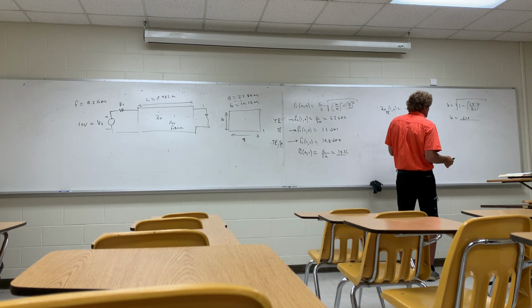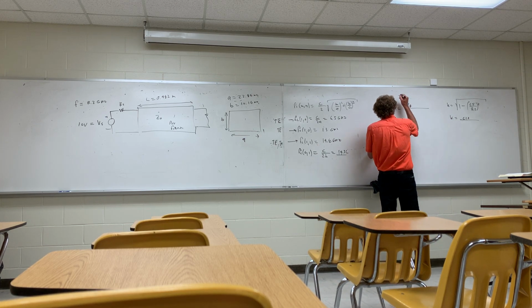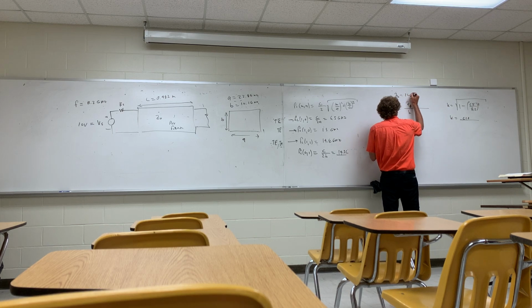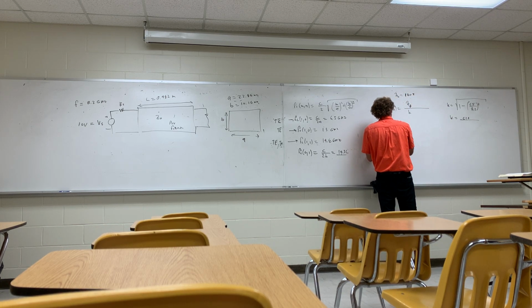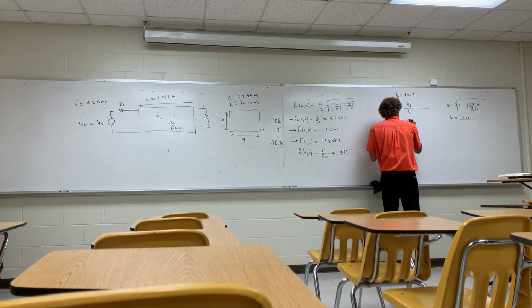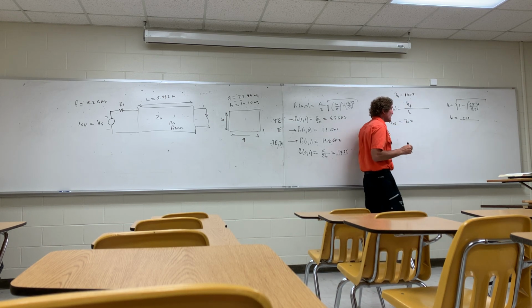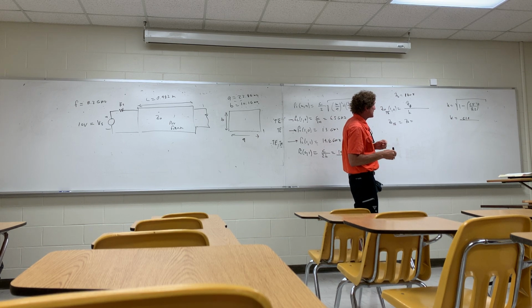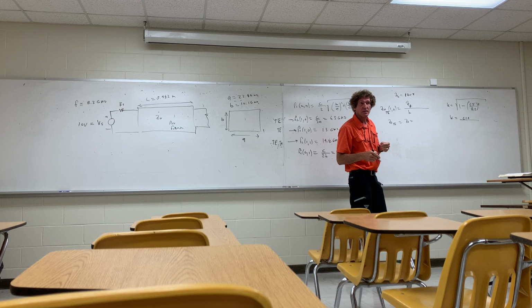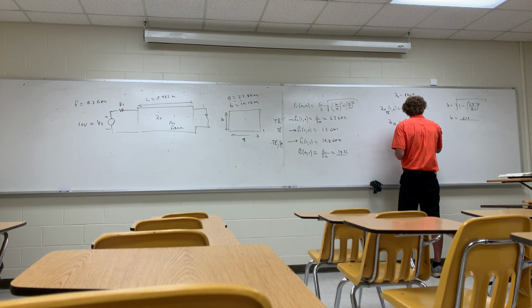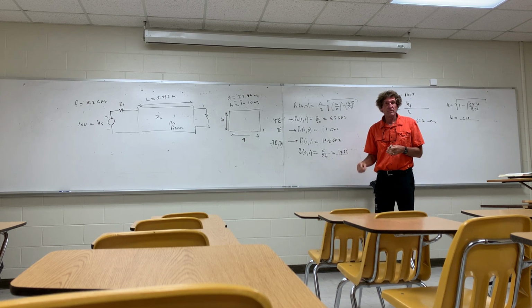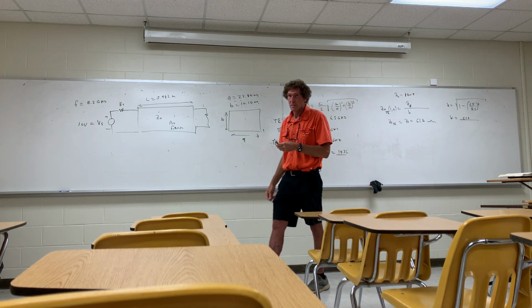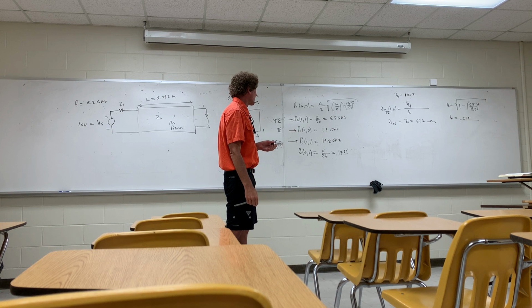All right, 0.610. Now this, beta naught, is just 120 pi, 377, so what is the characteristic impedance for the TE mode? I'll just call it Z naught from here on. It's 377 over 0.61. 628? Yeah. You getting that? 628 ohms, okay. I redid the 1 mode, and I think it's 16.15.